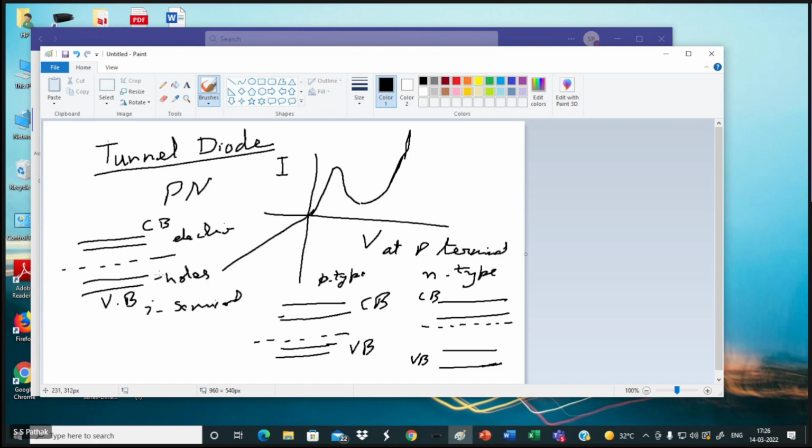So holes are positive, these are my electrons. When more electrons are put in, the Fermi level, which is the energy level with a probability of getting occupied as half, will shift to the conduction band in N type, and to the valence band if it is P type. Now when I make a PN junction,